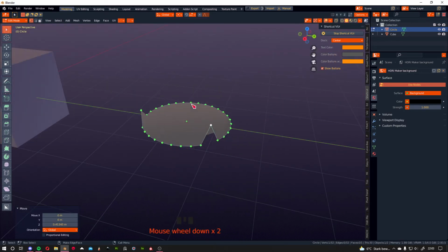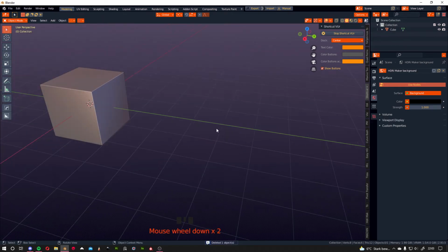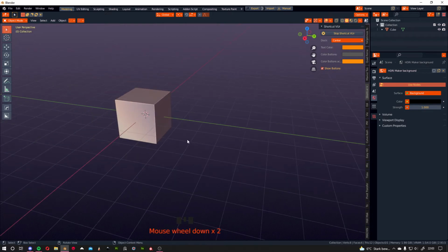That's the thing, we don't want to mess around with this. This is a key thing when it comes to 3D modeling. If you're working with quads, try to keep the quads flat. Most beginners do this wrong. Most beginners basically deform the quad, but we come to this later.